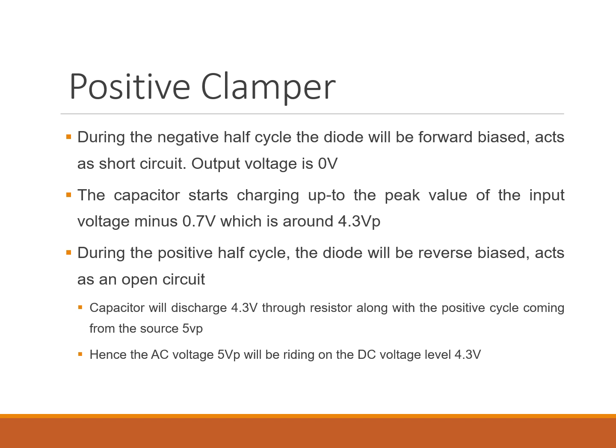The takeaways for this slide are that the capacitor sets the DC shift level, the diode controls when charging happens, and the result is a waveform that stays entirely above ground. And this matters because let's say you want to prevent signals from going negative, or you're aligning waveforms for ADC inputs, or you're trying to restore lost DC in a communication system.